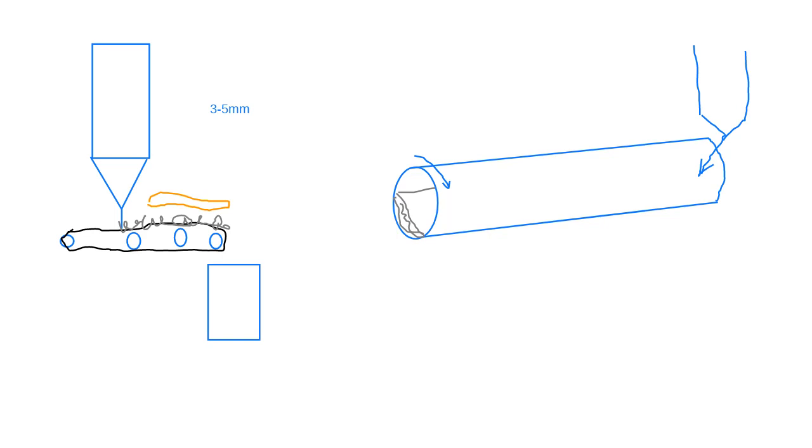So as this rotates, a particle will move along the wall upwards until it gets to the top, to some point where the angle is high enough that the particle can fall down, can roll down the surface down here and start again from the bottom. Now, what's good about that is on this surface you get radiative heating, and it is a continuously renewed surface. So that particle gets pulled up again to the top, and then it sees the radiation again.